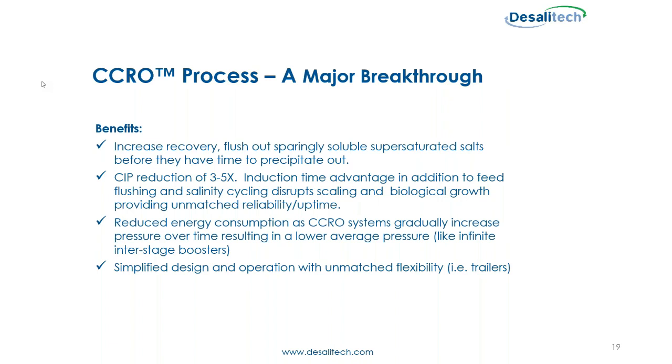And the other benefit is energy savings. So CCRO systems gradually increase the pressure over time, resulting in a lower average pressure. You can think of it in a traditional system, if you had infinite interstage booster pumps, and you can run this in a traditional design. If you wanted to add 5 stages and you put a booster pump between every stage, you'll find out it becomes significantly more energy efficient, but just from a design and capex standpoint, you would never do it.